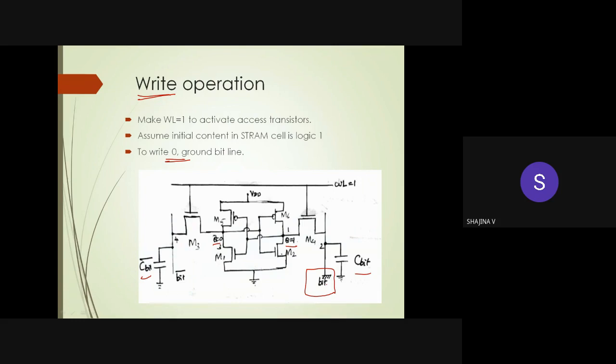Okay, now we are grounding the bit line voltages and enabling the WL signal by making it a high value. We can say the access transistors M3 and M4 become on. Now we can see the current flow between these points again, as in the previous case, you can check the current flow. Here Q is equal to 1.